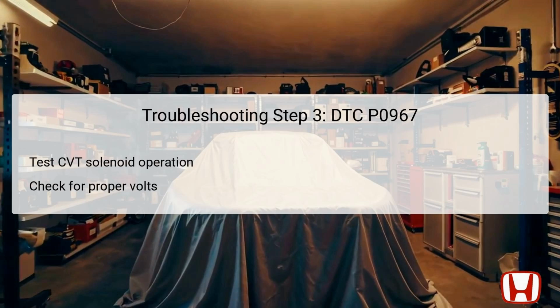In this troubleshooting step, the focus shifts to testing the operational integrity of the CVT-driven pulley pressure control solenoid valve itself. Using the HDS, it is important to check the voltage supply to the solenoid while monitoring its response during operation. The expected voltage should correlate with the specifications provided in the vehicle's repair manual.